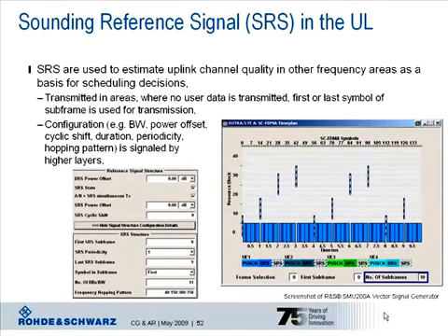The other physical signal in the uplink is the sounding reference signals. Sounding reference signals are used by the base station to estimate the quality of the uplink channel, to be used as a basis for scheduling decisions, meaning where a UE should transmit its data. The eNode B is free in its decision to configure the bandwidth occupied by the sounding reference signals, power level, etc.